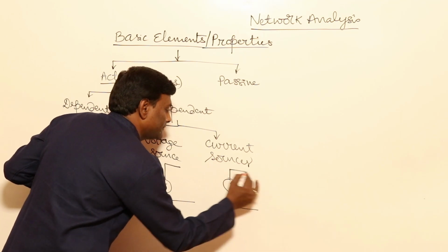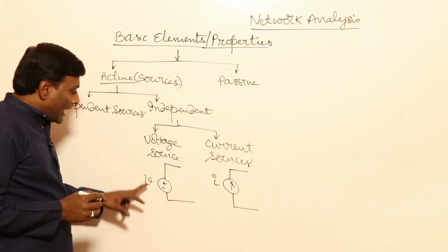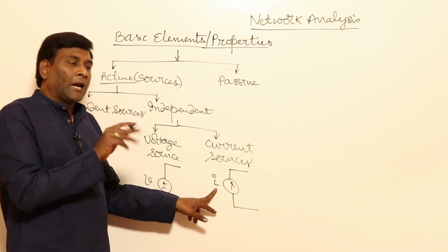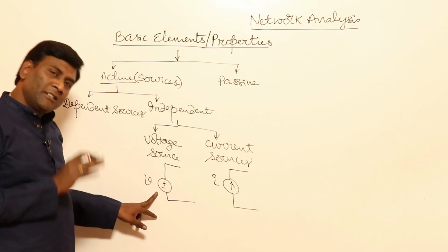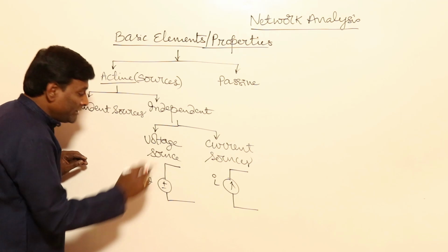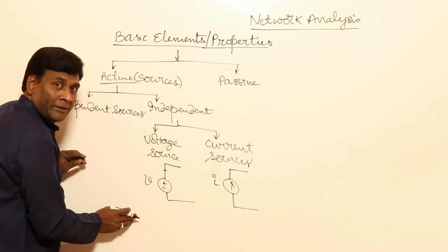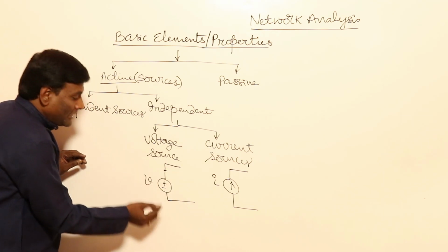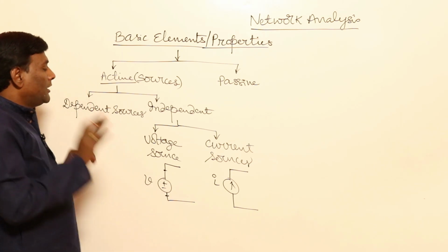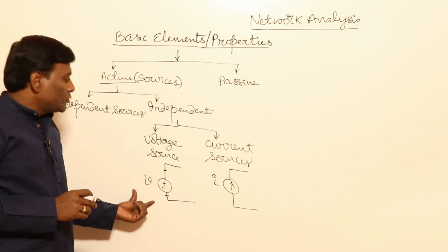Leave that. Now this particular voltage source we can show like this, and the current source we are going to show like this. Okay, I am using small case letters. Why? Small case letters are going to be the superset, capital letters are going to be the subset. So it can represent DC also, AC also. Okay, as we discussed in our previous session, this terminal is at more potential compared to this one by V. That V can be negative. Getting my point, right?